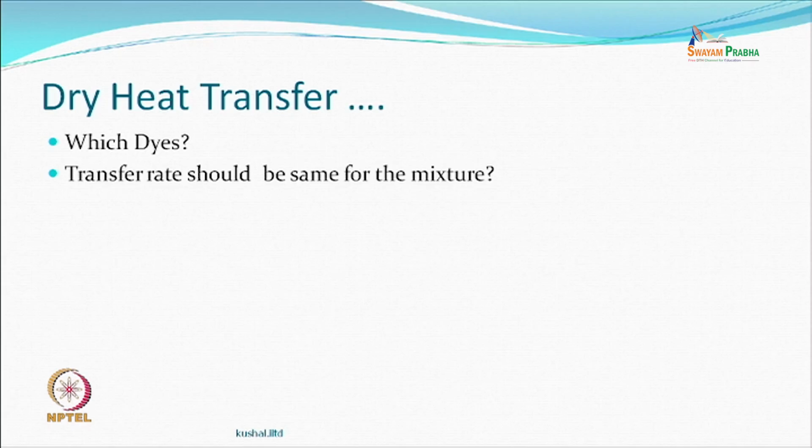This one has to work carefully in consultation with the dye manufacturer. Dye manufacturers give you charts which have all the experiments done on the dyes, and when you try to mix them up, you should know which dye to mix, because you will be using mixtures of dyes to get different shades. The temperature where a reasonable amount of sublimation takes place may be different for different dyes.